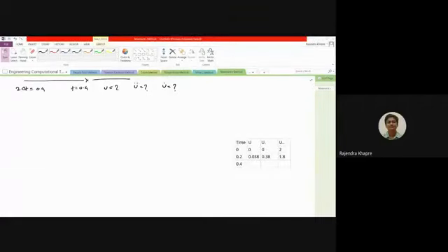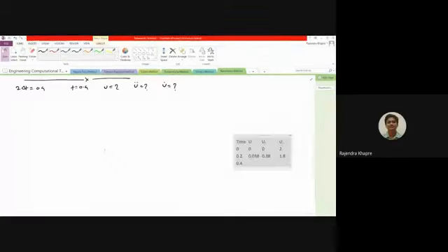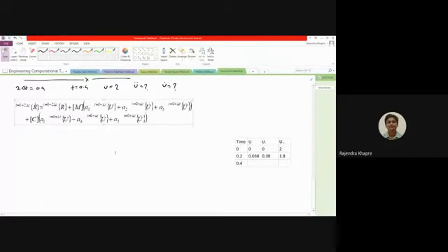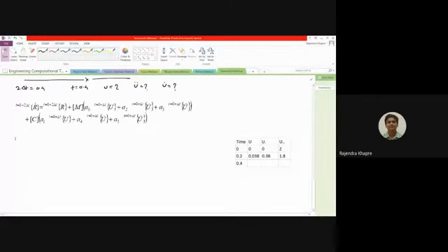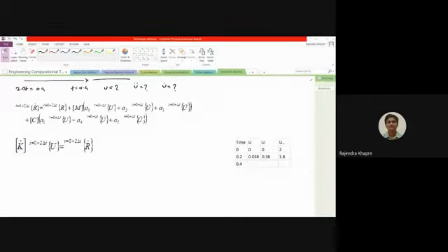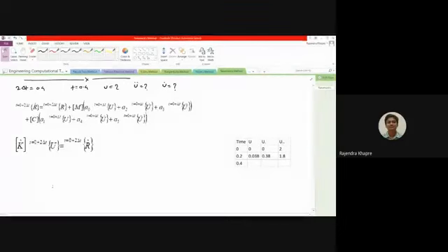For example, if you take the value of the effective load vector, every delta t will now be increased by one more delta t. So this is the expression which is there in front of you. Then you can use the stiffness expression over here to calculate the value of the unknown displacement, and further you can use an expression to calculate the acceleration.